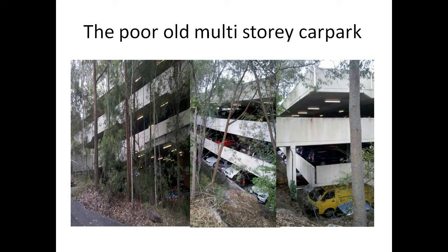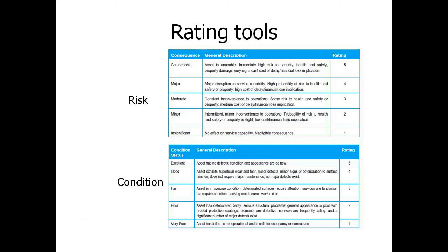Chunks of concrete falling on cars, stains from the concrete, from calcium and lime coming through, rust stains coming through and falling on cars. Major problem. So considering how the building's responding and looking at the isolated areas where the building or asset's starting to fail, and then saying, well, is this a problem everywhere? And then responding to it correctly to ensure that the asset or the building is safe, is secure, and is not going to deteriorate. And if it does, then you have a plan in place to rectify it.